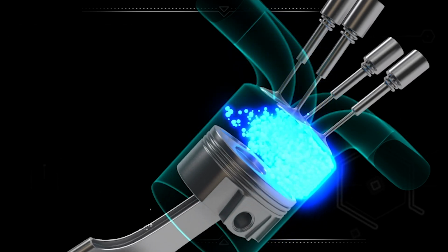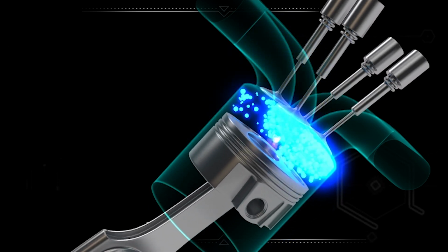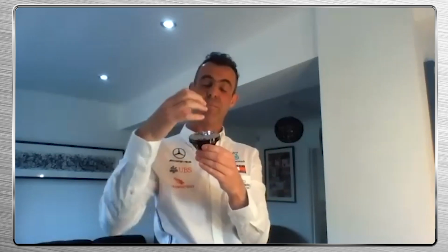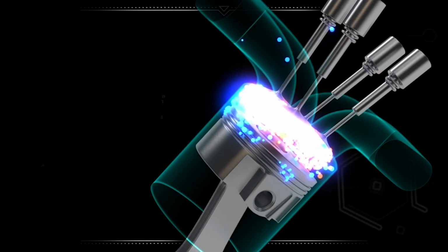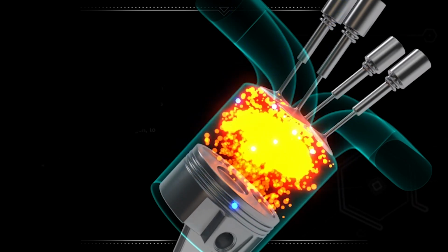What's happening there is the volume of fuel and air is getting compressed and getting prepared. The pressure goes up, the temperature goes up, everything's ready, and it's just waiting to combust. And then nearing the top, we spark the spark plug and we get a combustion event. That beautifully ready, prepared air-fuel mixture will then combust and you get the power stroke. So the piston is then driven to the bottom of the stroke, and via the conrod and that offset crankshaft, you then get a torque applied to the crankshaft, and that's where the power's coming from.